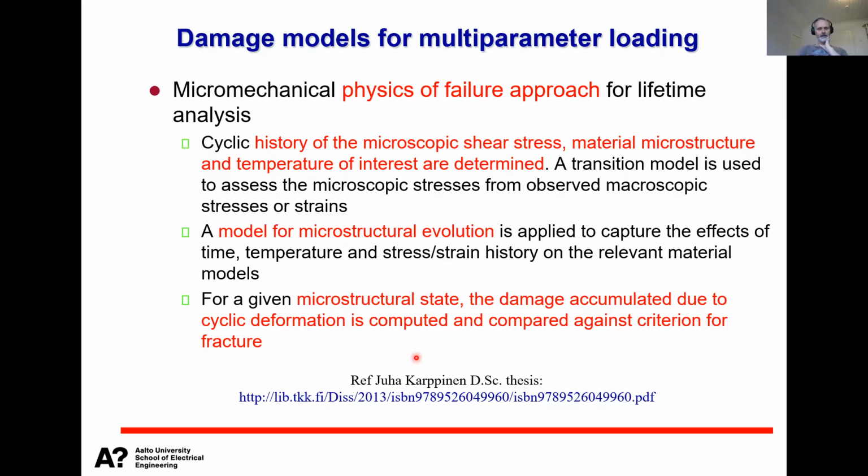He did his PhD thesis on how you should approach these cumulative stresses. You should understand how all these stresses affect the materials themselves: how the microstructure and defect structure evolve, and how the strength of the material possibly decreases because of this evolution.